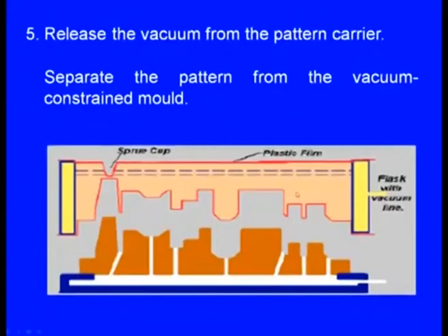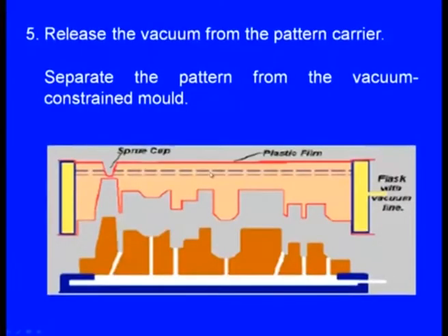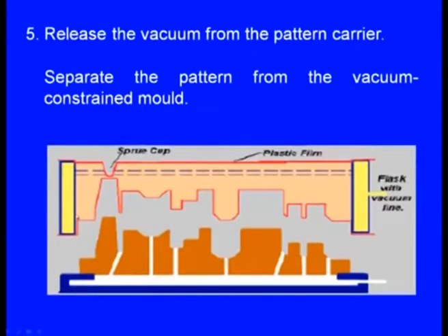Now, you see here, this is the sand mold. Now, remember the sand mold is comprised of dry and fine sand, no moisture and no clay. Now, then the question is how it is bonded? Because of the vacuum. This sand now it is concealed by polymer film. At the top there is polymer film or the plastic film, at the bottom also there is plastic film.